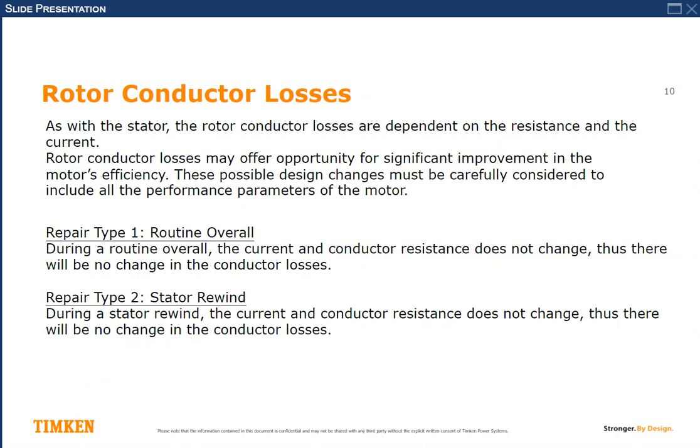Now let's look at the rotor conductor losses. Similar to the stator, the conductor losses are dependent on the I squared R, or the resistance and the current, so they are load dependent. Here as well, in case study 2, I'll show you some of the interesting work that we've done, taking an old machine design and see how we can improve it. Now this is different from the stator because in an induction rotor, in general, the rotor bars are not insulated. So it's not like I can use better insulation and then put in more copper.